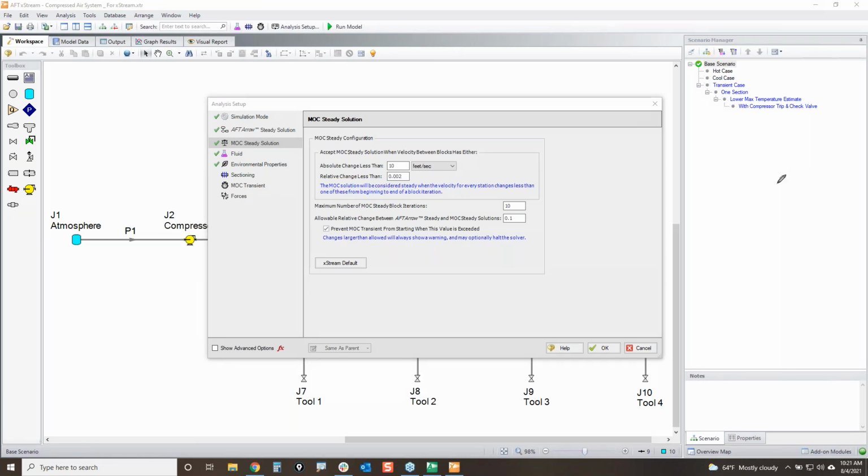And so if we were to use the method of characteristics for solving the transient mass, momentum, and energy balance equations, even though that's a different method than the Newton-Raphson method here, these solutions should be equal and they should give the same results.